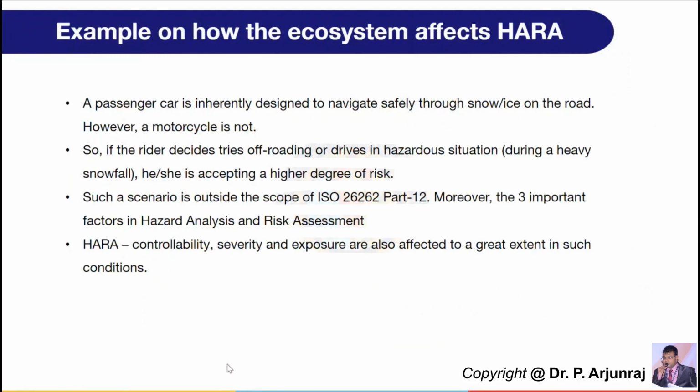So you also need to ensure that the safety is not getting affected with dual means. Even if a primary failure happens, it will not affect the overall thing. Even though there is a failure, no hazard is going to happen, because one circuit completely fails but the vehicle still gets stopped. This failure can be because of some error or some fault. That's why I told you all errors or faults may not lead to failure, and all failures may not lead to hazard. But it's very important how best you are reducing the faults in the system or component, which will have a very good impact on the overall safety features.